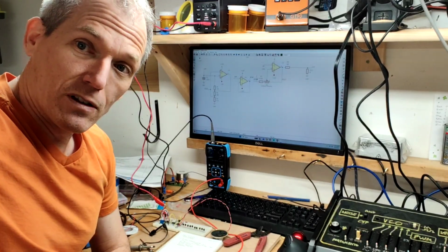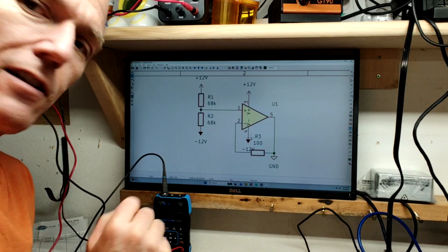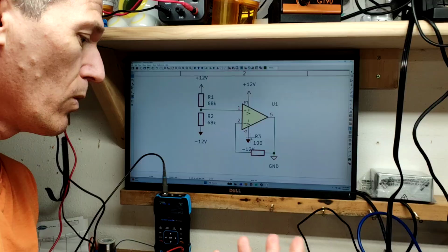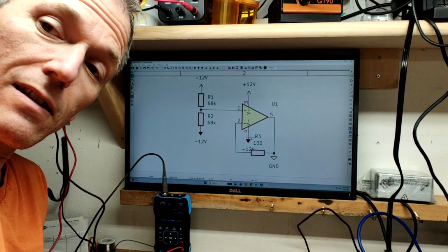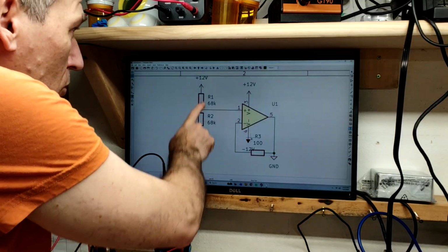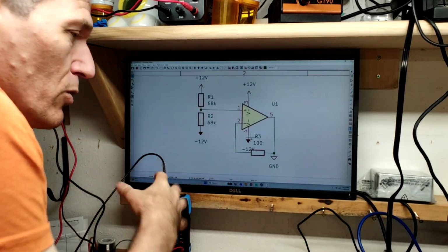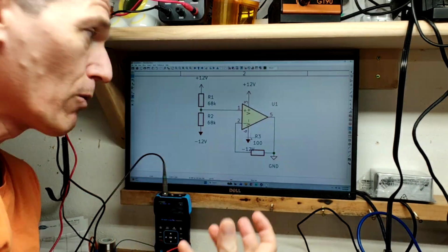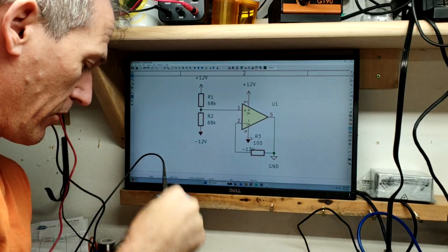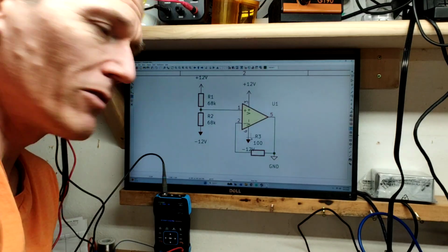I want to show you the schematics. Okay, so my power supply doesn't have a ground. It just has a positive and negative. So for most of these audio circuits, we need a minus voltage source, a positive voltage source, and a ground. And so what we need to do is create a ground. One way to do that is with an op amp like I've drawn it here. The circuit's actually implemented with a buffer. Maybe we'll get into that later, the difference there.